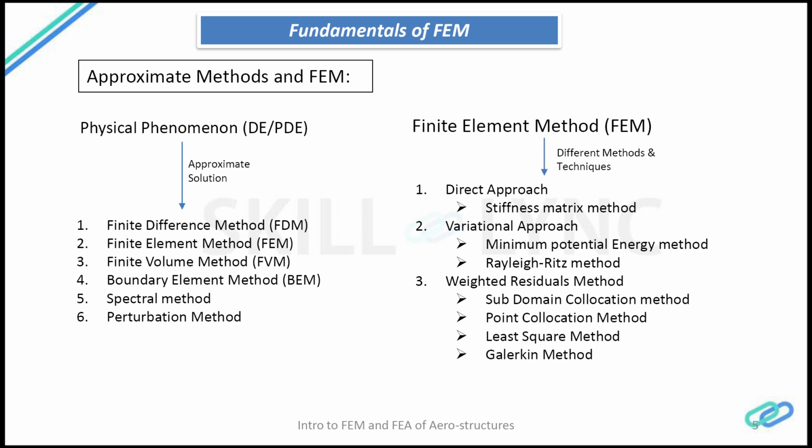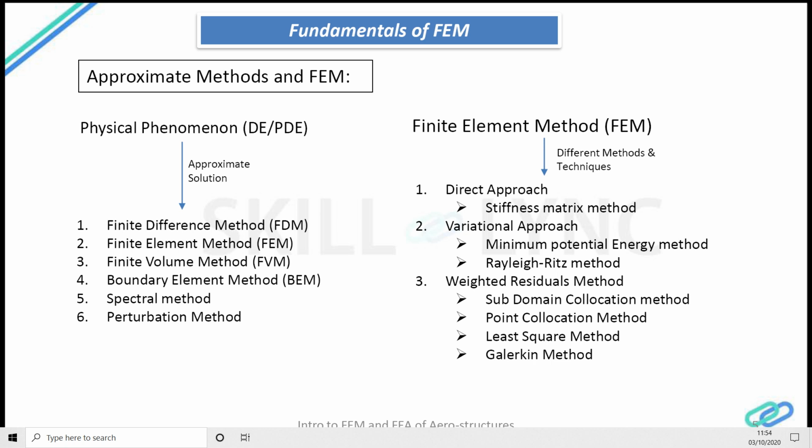And it is in the form of a polynomial equation. And then they solve the equation to find the unknowns, which are nothing but the displacements and forces. Similarly, in the weighted residuals method, you have an equation which is very approximate, and then there will be functions of both the independent variable and the constants, called the residual.